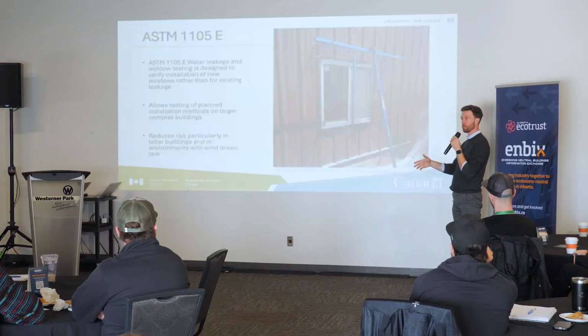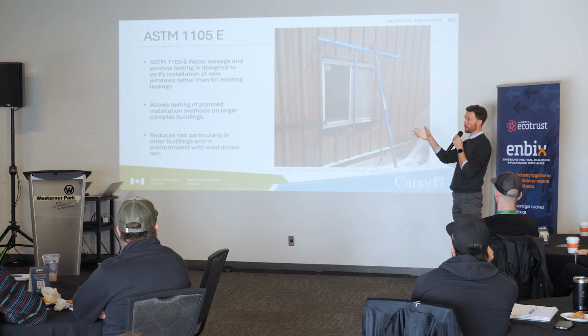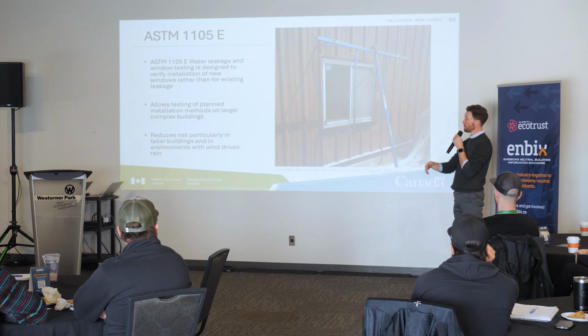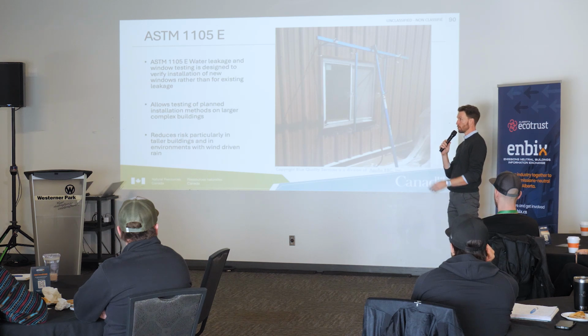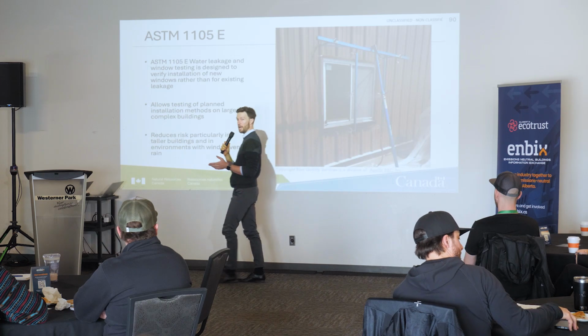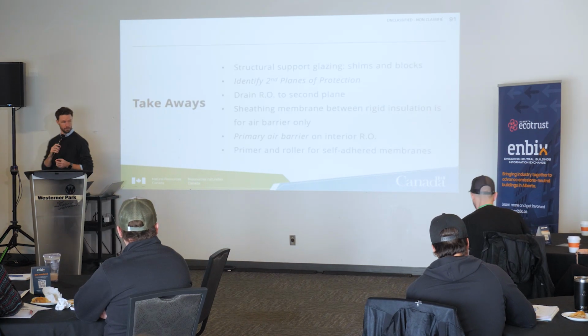I think they'll walk you through it, but two different installation methodologies: the 440.4 install method, and then an updated version for a good, better, best, a better install, and then put under this pressure test to see how they performed and where the water leaks. So I'll run the video, and then we'll have a few minutes after that to talk about what we saw in the video and to address any questions that come up from this presentation. Okay. Sound good? Sounds good.